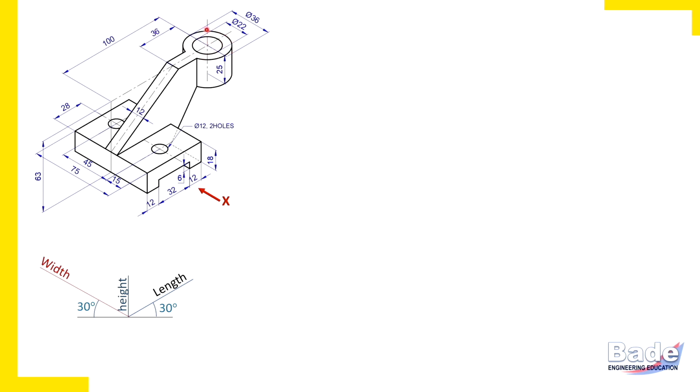So we have to add the radius of this curved edge, and this curved edge has diameter 36, so radius is 18. So 100 mm plus 18, extreme left to extreme right, that is the overall length of the object, and it is 118 mm.